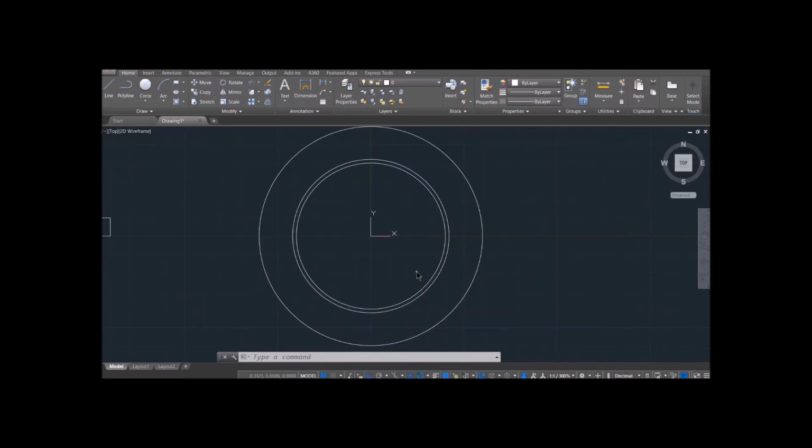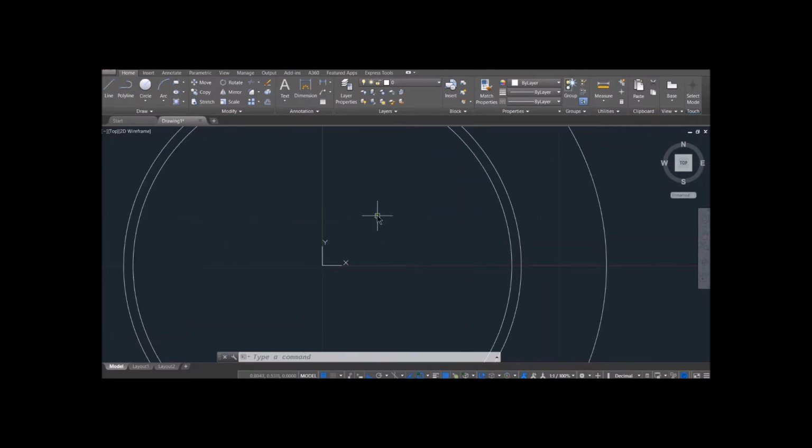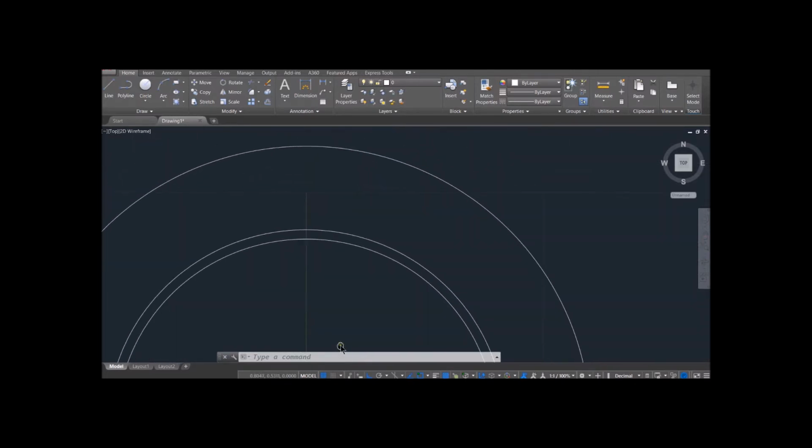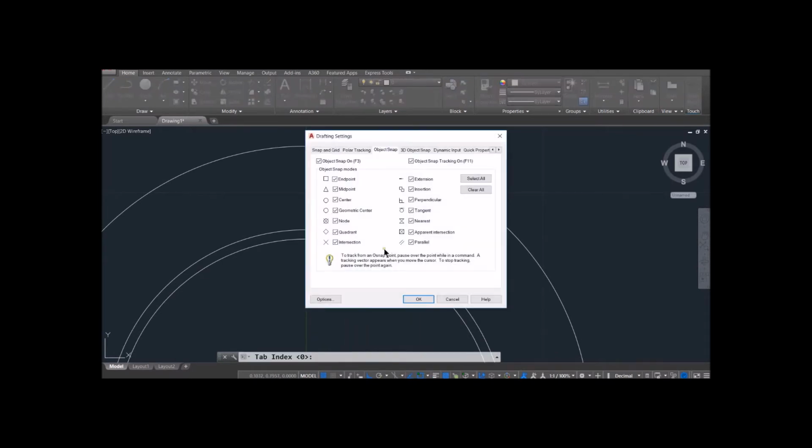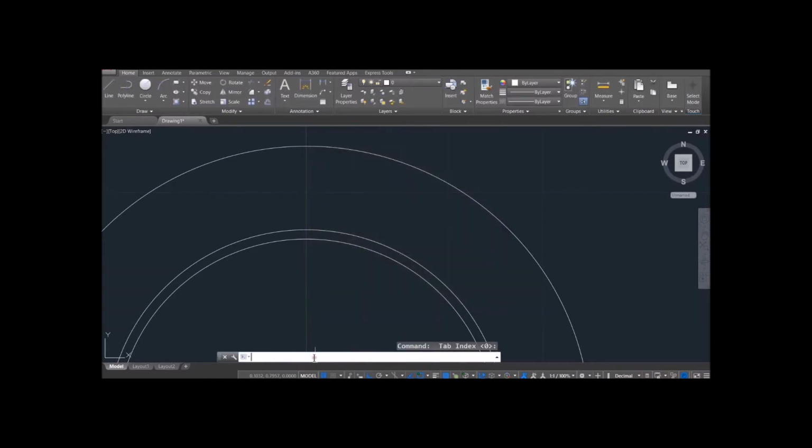Next, let's put some ribs on here. I'm going to overcomplicate this just to show you a few more drawing tools. I'm going to start with a simple rectangle. There's all your snapping tools. Make sure you have those set to what they want to be. So rectangle, this will let me snap to the center, and I'm only making half of this rib right now so that I can show you the mirror command, and then we can review the trim and the join tools after this too.